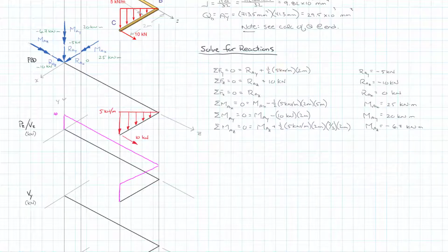And I'm just going to note that this is an axial force in here, and to be fair, it's axial tension, whereas this is a shear in that direction. Now, we're not actually calculating anything out at CB. It's not our area of interest in this problem, but it is worth noting how that changes because these are all drawn in the global coordinate system. So I'm going to go down and I'm going to do the force in the Y direction right now.